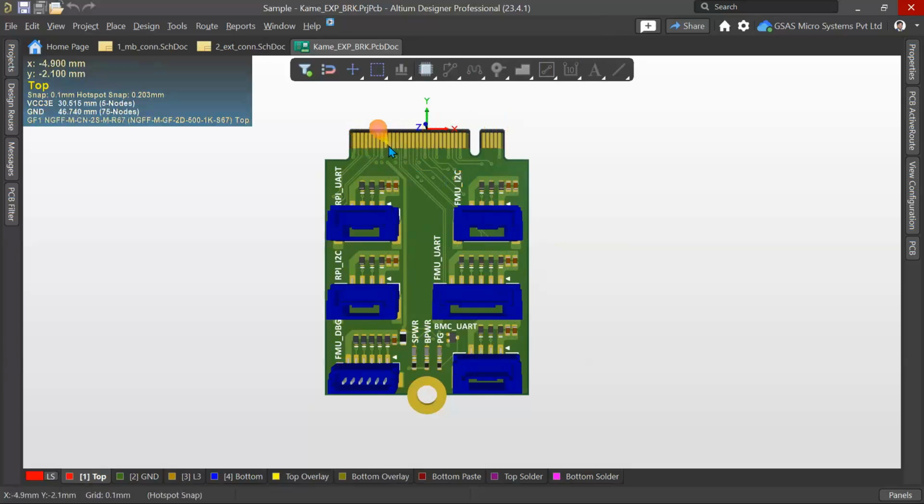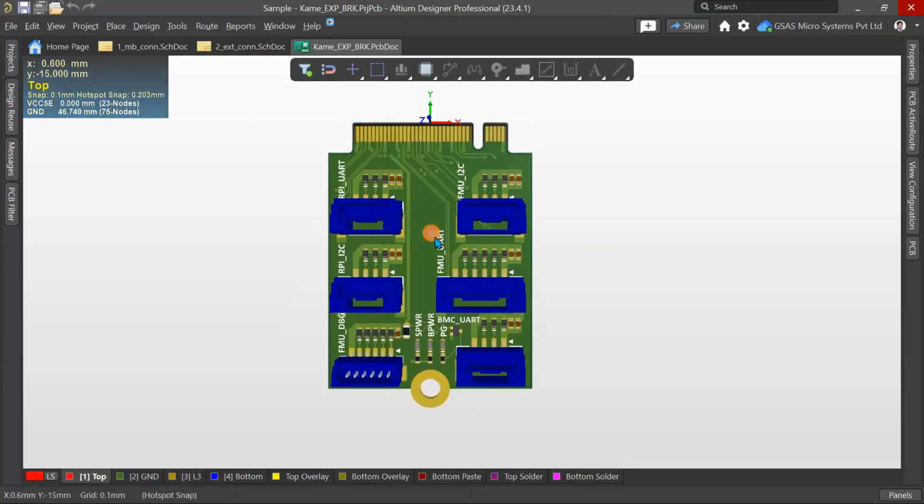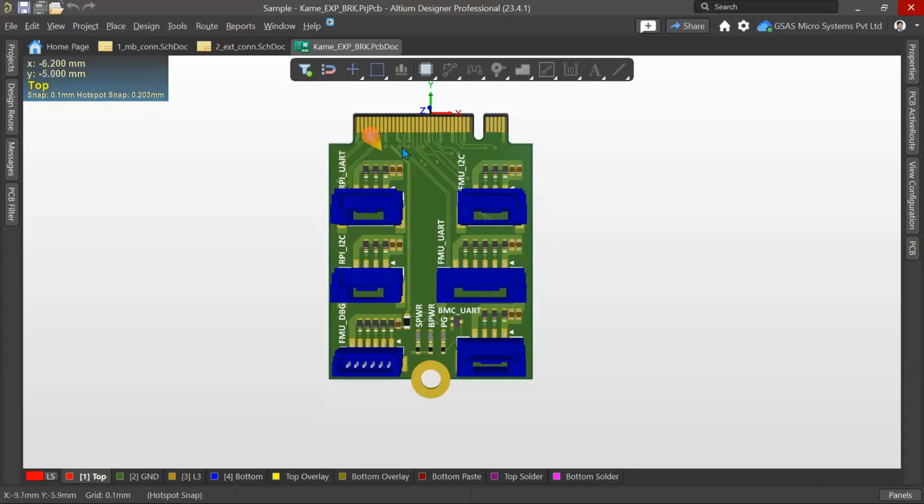That means instead of drawing the circuit one time after another, if you have a design reuse block, you can place the circuit and complete it faster. And if you assume that this kind of circuit will be useful for your upcoming designs, you can also create them as a reuse block. With this reuse block, you don't need to repeat the circuit multiple times. You can just place the same design multiple times, and it will be updated to the PCB, which will save you a lot of time. Now let us see how we can create a design reuse block from this circuit.